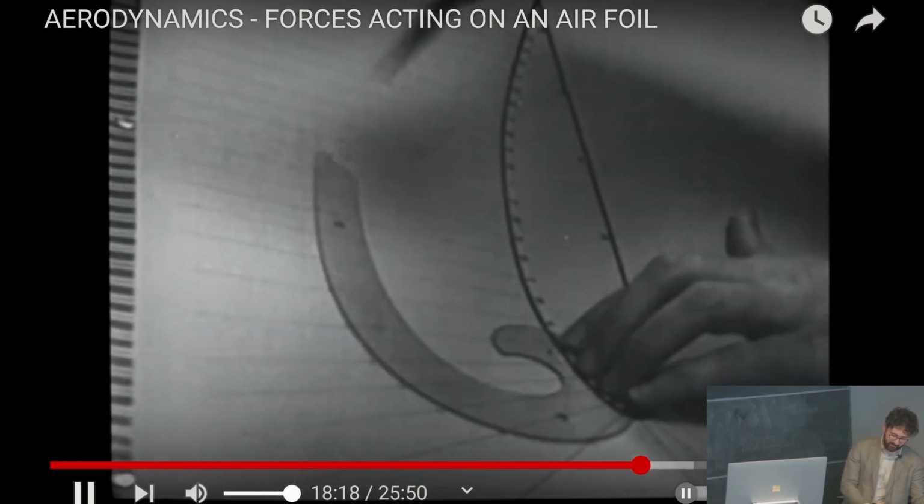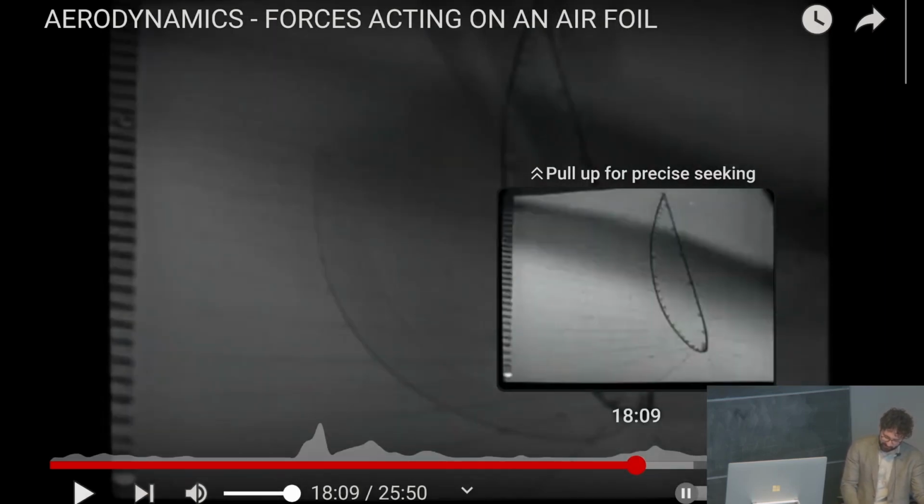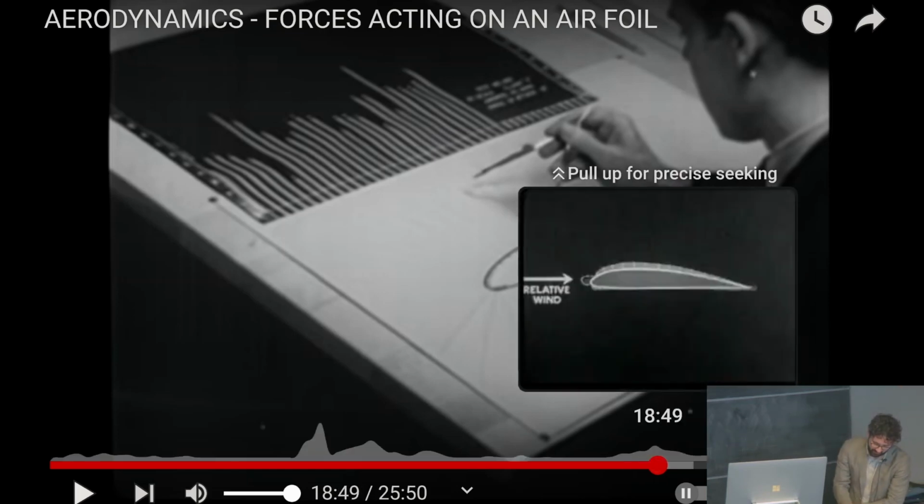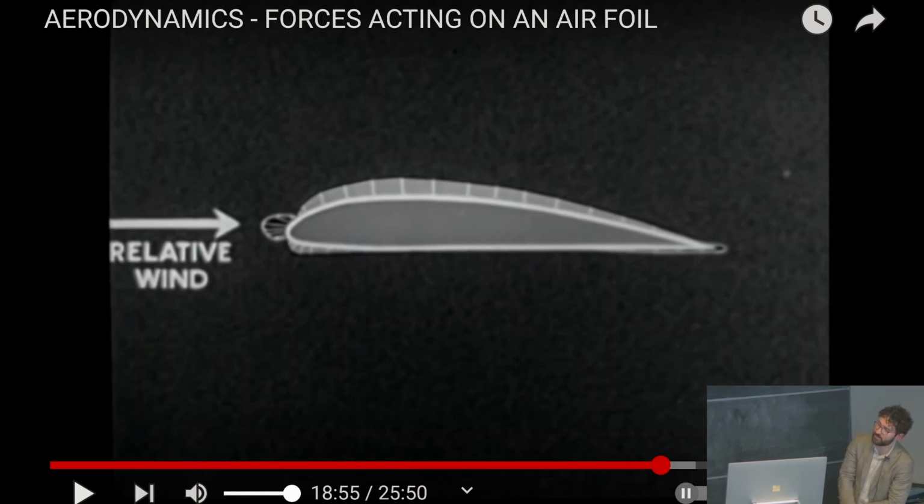So then basically you have pressure measurements. Just to clarify, the tubes are connected to all the different points along the airfoil surface. So you've measured the pressure at the surface, but you're going to plot a distribution of pressure over the airfoil, and that's what a typical pressure distribution looks like. The top of the airfoil is the suction side, so that's going to be a negative pressure, and the bottom is positive pressure, but they usually draw it like that. That's basically how they used to measure airfoils.